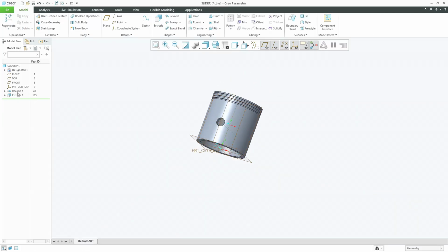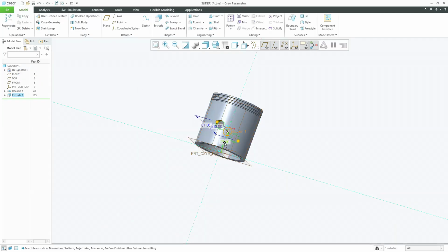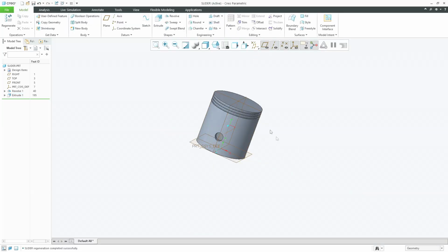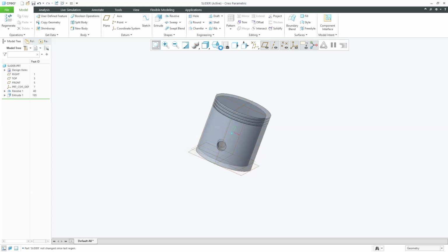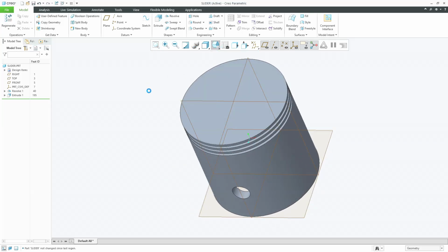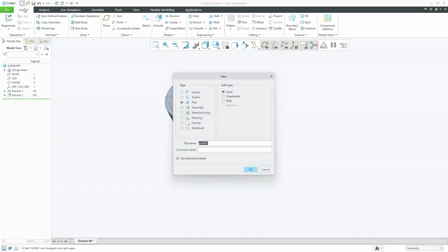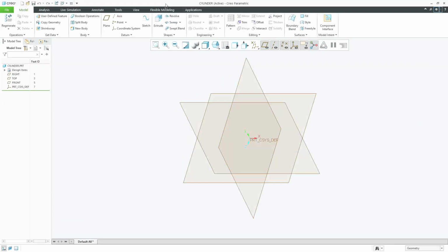I would like to reduce the height of the hole position from 25 to 20. So this looks good, and this I'm considering as a cylinder which is a kind of slider content. The last and final part, we are going to create a cylinder base where this piston moves up and down. So I'm just selecting this, I'm converting this as a cylinder. Just click OK here. And the same as piston, we are going to use this as a revolve command.